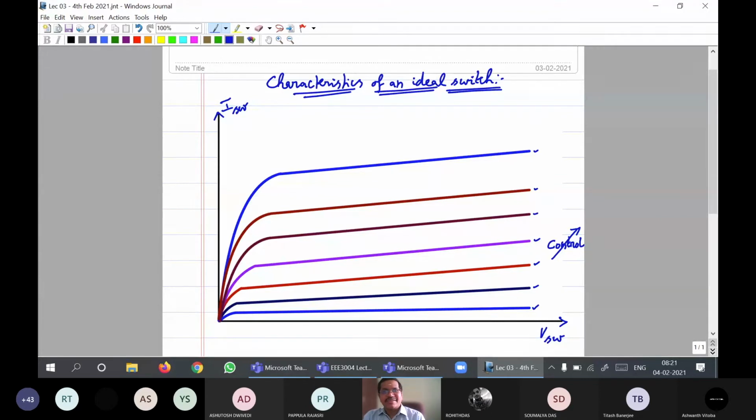Don't take much time, I'm just asking to review certain things. If you take a BJT, you have three terminals: collector, emitter, and base. Among these three terminals, two will be power terminals, which means you apply the input voltage. One terminal will be the control terminal, wherein when you vary that control parameter, the VI characteristics can be varied. This is the principle based on which we categorize the terminals as power terminals and control terminal.